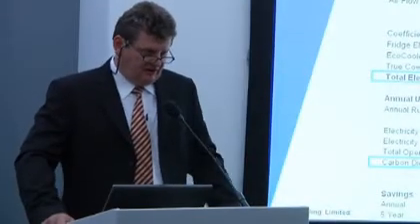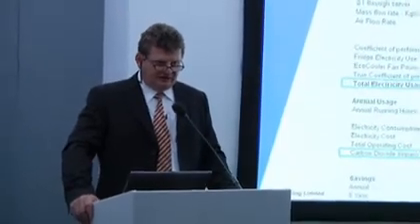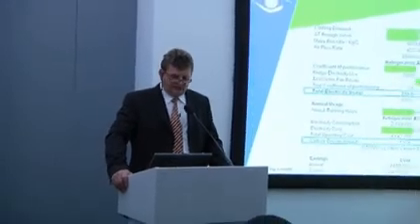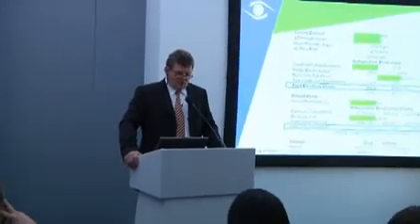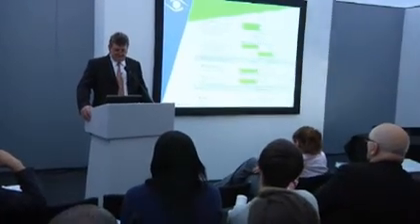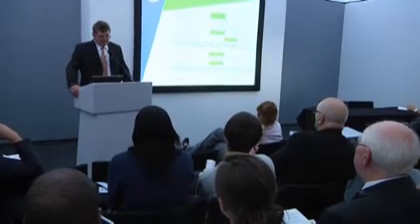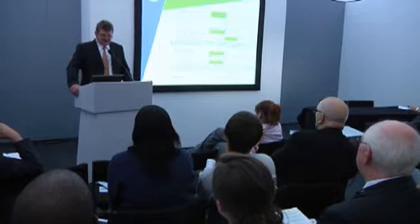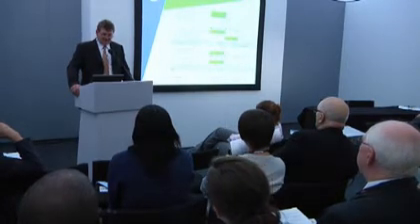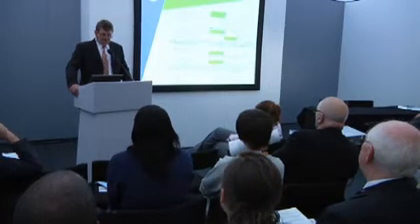When we look at a data center, a lot of people do get a little bit misled in that they concentrate a little bit too much on the actual cooling load. There's a little bit more to it than that. What we're actually trying to do is give all the servers the right volume of air. Wherever that air comes from is irrelevant, but you've got to give it the right volume. Now, 500 kilowatts of servers actually adds up to about 42 cubic meters per second of air. That's a lot of air. Where does it come from?